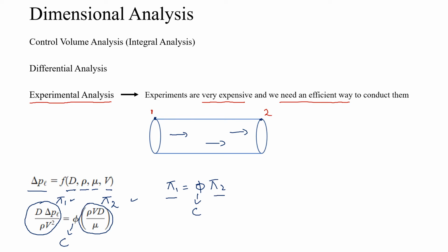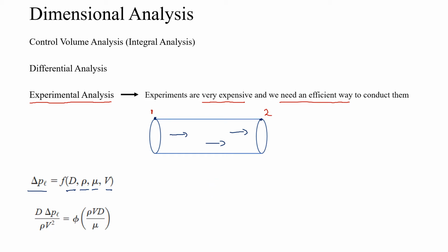So how will we do that? This is what dimensional analysis is all about. How will I arrange these terms? I will arrange these terms so these terms come out to be unitless. These terms right here, this term and this term, their units, all of these variables, the diameter, the pressure drop per unit length, the density, the velocity, on the left hand side, if I write their units, they will come out to be unitless. These units will cancel out each other, and this term will be dimensionless. And this term will be dimensionless.